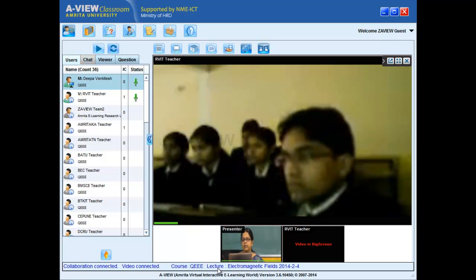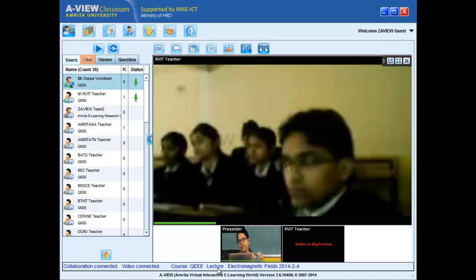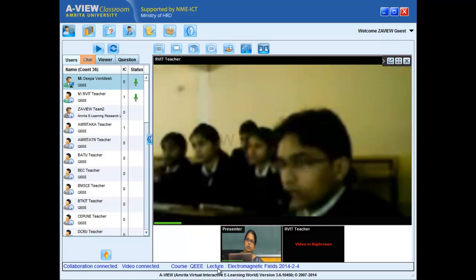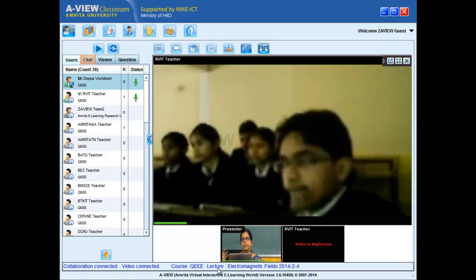So the reason why we are using phasor notation is to say that we know how it's going to change as a function of time. That's not going to change in the transmission line because it's a linear system. If I've excited the system with a frequency omega, the system is going to respond with a frequency omega and none other than omega, right? So then time derivatives become very redundant, they become just j omega multipliers. So that is the reason why we are using phasor notation.